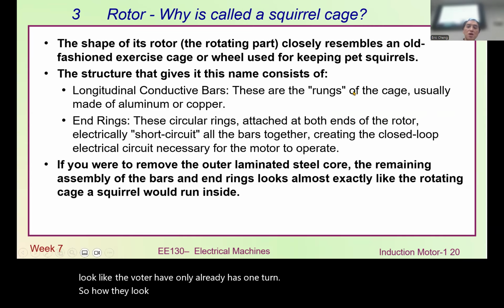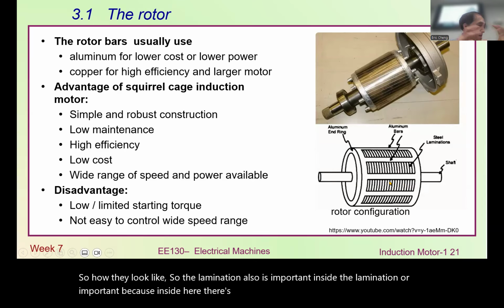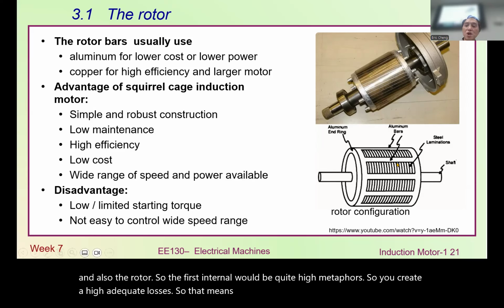The lamination is also important. Inside the lamination is important because there is also high magnetic flux produced by the stator and also the rotor. So the internal flux will be quite high, and you create high eddy current losses. That means the lamination here is also quite important. But the frequency inside the rotor will be quite special.